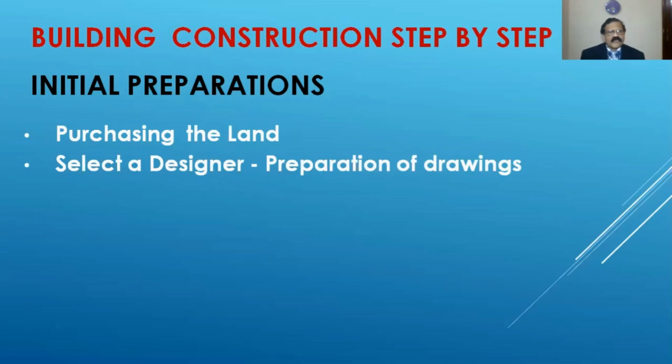Second step is to finalize a designer or an architect. He will be preparing all the drawings required based on the latest building rules. The designer will also arrange the soil testing. Soil testing is very important to see what is the soil strata in that particular location, and based on the soil condition we have to design the foundation.